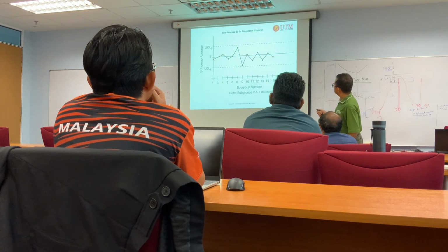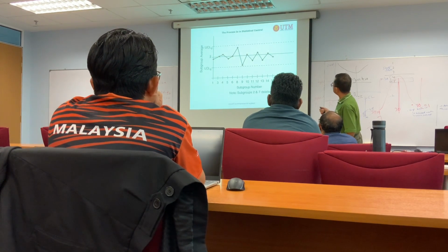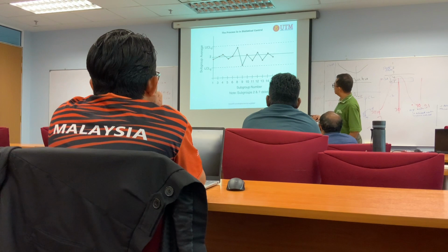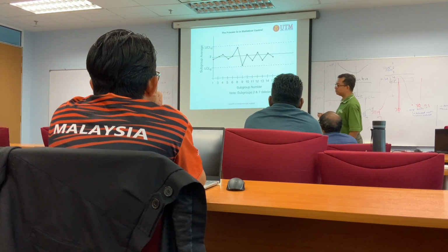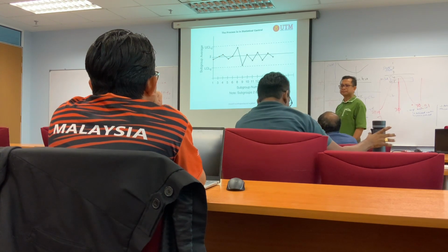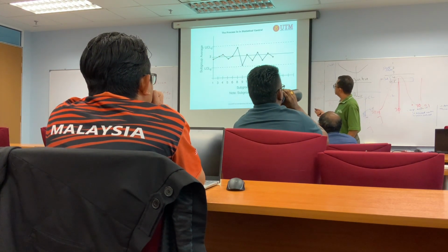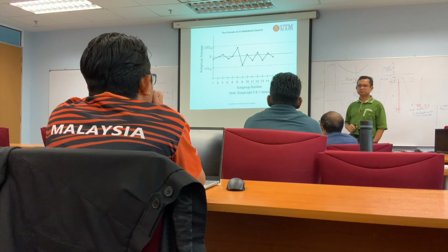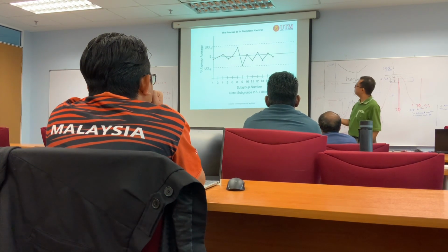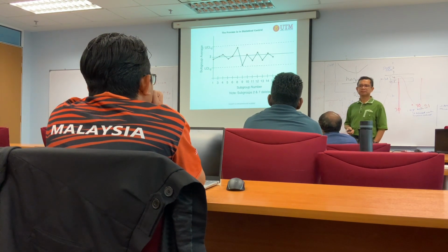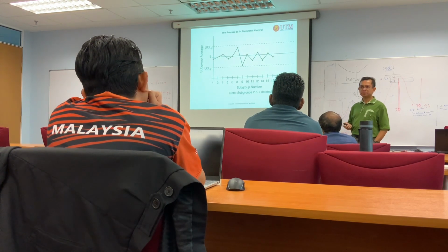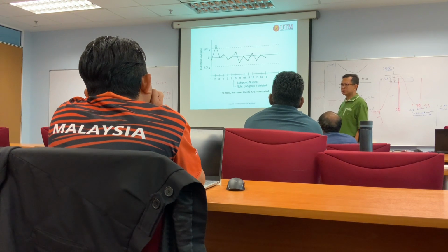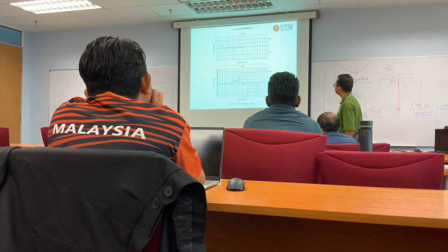So although we agree with this, of course the product that represents the subgroup number will be delivered to the customer. But this is something that alarms us. What should you do? You have to investigate. Because this is pushing towards the upper limit and this is pushing towards the lower limit. You have to find out why. Stabilize the process. Maybe something is wrong. That's what we're going to discuss next week. Ask 5 Why and so on.